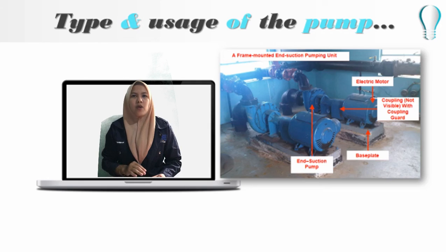Some manufacturers offer a standardized line of end suction pumps referred to as ANSI end suction pumps. This type of pump is built to a common set of design standards and is even dimensionally interchangeable between manufacturers. End suction centrifugal pumps are particularly popular because they offer a compelling combination of comparatively low upfront costs, acceptable service life, good efficiencies, and design flexibility.